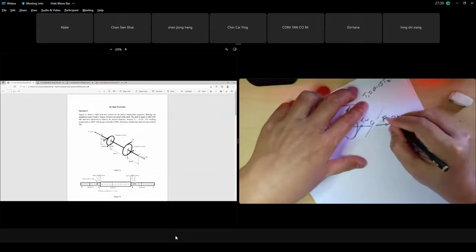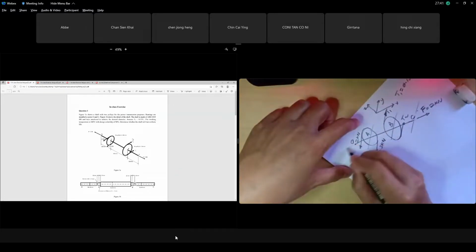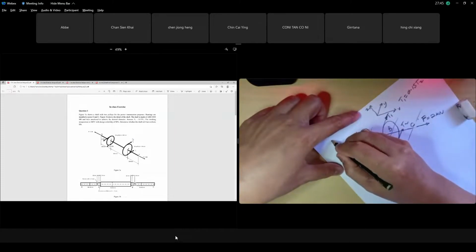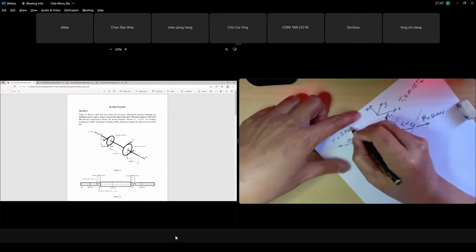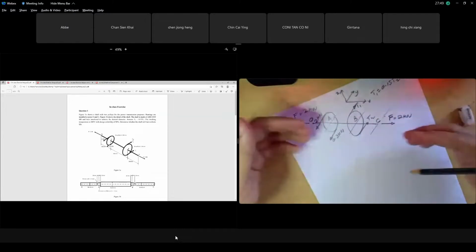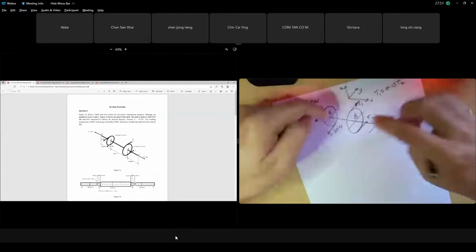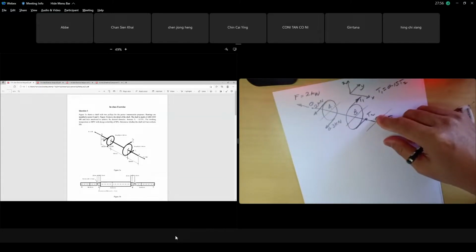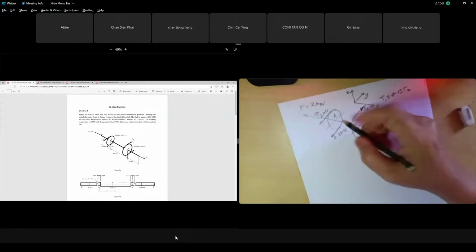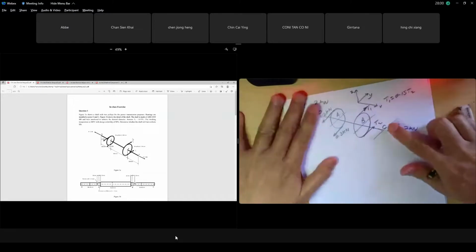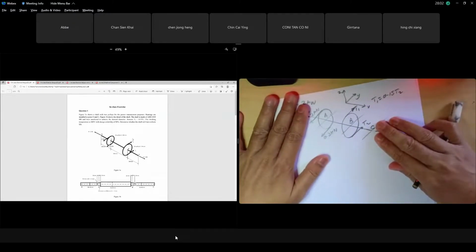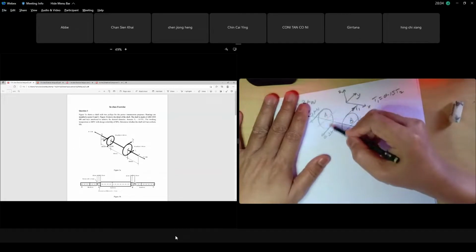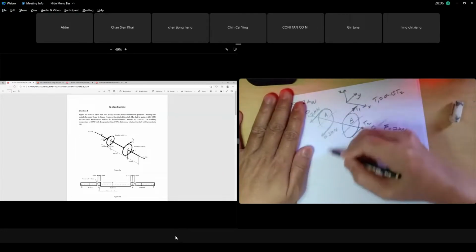It's an external axial force at the end of the shaft, pulling the shaft, 2 kilonewton on both ends. So it also gives the shaft axial stress. Be careful about it, because you have to combine your sigma and find which point is critical. Normally you do your case without axial force, but this one has it. Normally you draw the shear diagram, the moment diagram, and find the maximum moment.